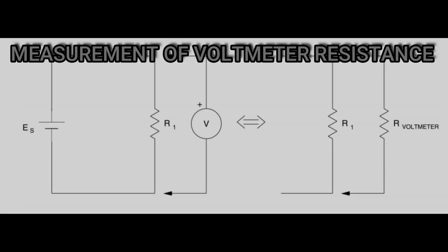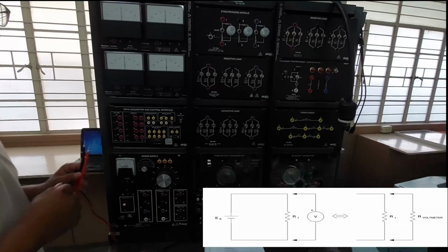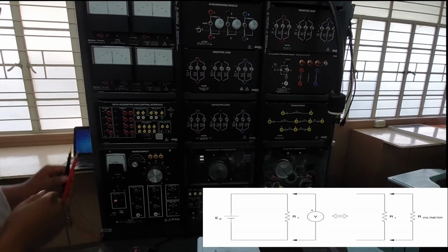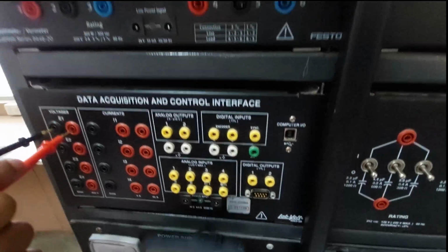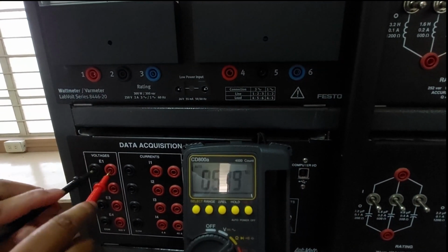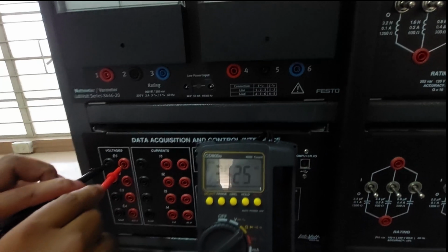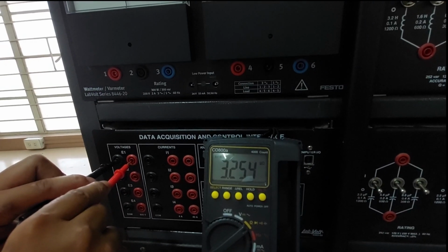The volt is the measurement unit of potential difference, and voltage is measured with a voltmeter. Voltmeters are always connected in parallel with the circuit or component. They have a high internal resistance to minimize the amount of circuit current that will flow into their terminals. Their effect on the circuit operation is then minimal. Note that the polarities marked on the standard analog meter terminals must be observed to obtain a positive reading. If the connections are reversed, the reading will be negative.